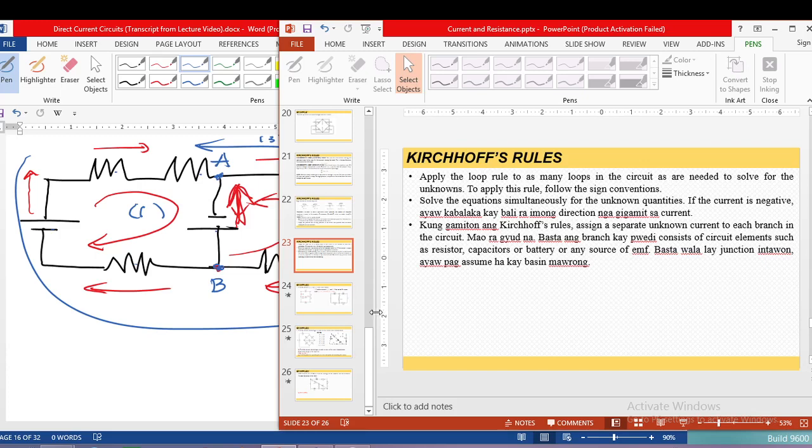So what will happen is you will still again use the negative current to find another unknowns. Okay, kasabot mo? So gamiton gyapon to ang current nga negative. Then at the end, i-conclude ninyo: therefore, the current that I assigned for R1 is negative. That means that it is in the opposite direction to my assigned current. Okay, kay kung i-positive ninyo nga ga-solve pa mo, your answer will be incorrect all throughout. So that will affect the equations. Okay?